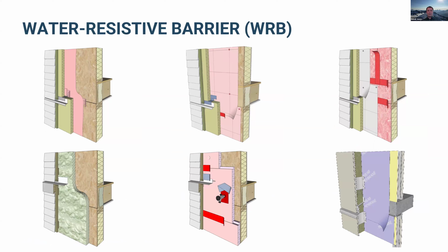And that brings me nicely into the next layer, the WRB. So this is the inner layer of the rain screen. So this is the inboard side of the cavity. It's most often going to be a membrane, but it's not always. There's lots of different ways to do this, right? We've got a picture here of spray foam that can actually work as a WRB. We also sometimes see just insulation, board insulation that is taped at all the seams.